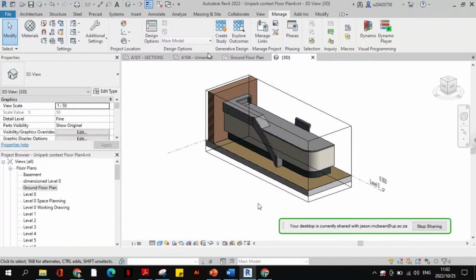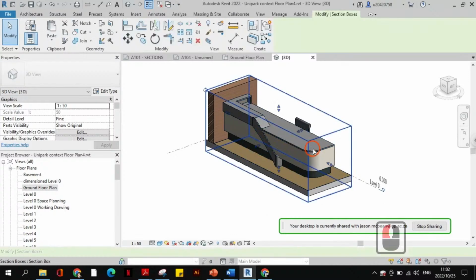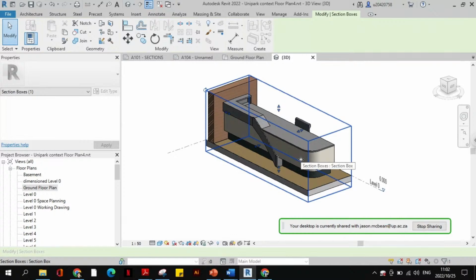What you can do is, if you want to break this thing up as this in-place family, you can actually put the worktop in its own in-place family. You can put this structure in its own in-place family and this in its own in-place family, and then make everything an assembly. Because that allows you to explode this thing. If you want to take a 3D view and explode it, then you can. Because otherwise it's all in one in-place family.